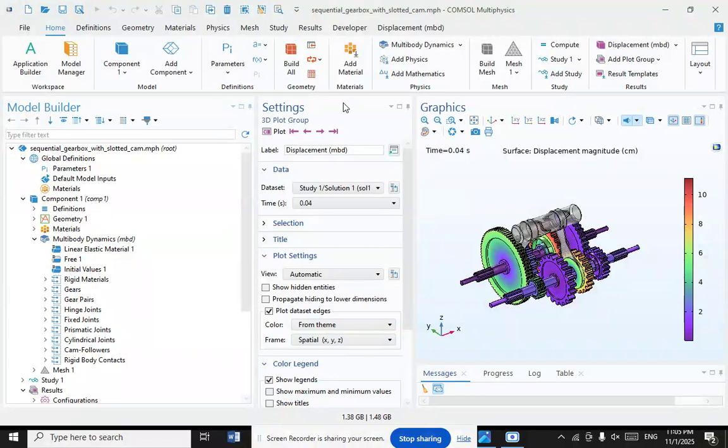Most transmissions include a lockout mechanism to prevent reverse gear from being accidentally selected while the car is moving forward. This can take the form of a collar underneath the gear knob, which needs to be lifted, or requiring extra force to push the gear shaft lever into the plane of reverse gear.